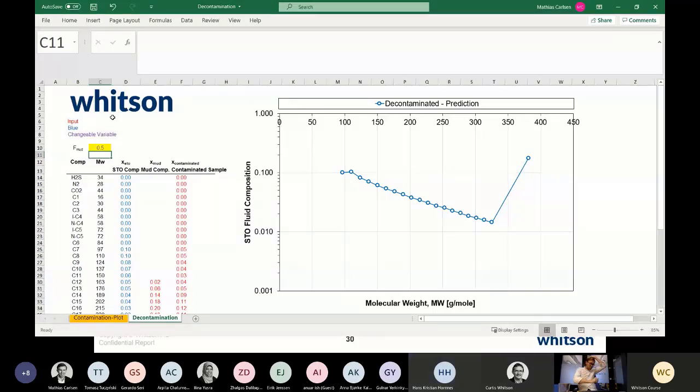Curtis, any comments on that before we jump to Gerardo? Yeah, no, I think everything is clear now that it can be more complicated than what the lab assumes, and if it is, then the engineers who've gone to this course or have studied the problem can handle that, but you need an ability to describe molar distribution separately for the reservoir fluid and the oil-based mud. And each well may have a different oil-based mud. And in general, though, the reservoir molar distribution is uniform throughout the field.